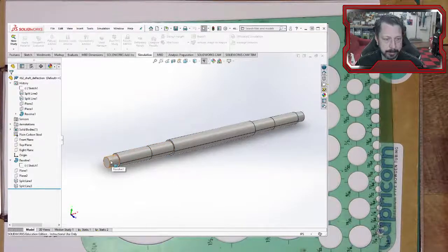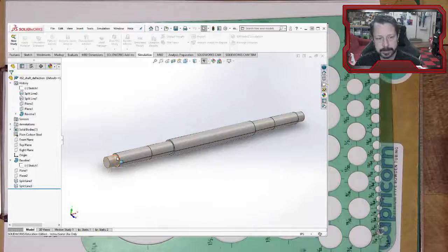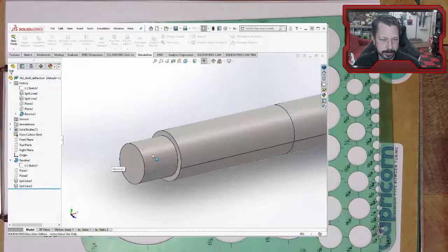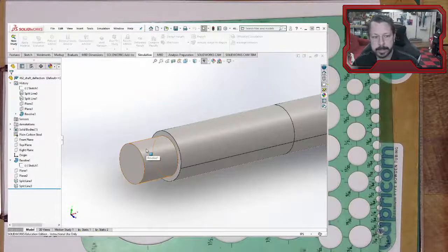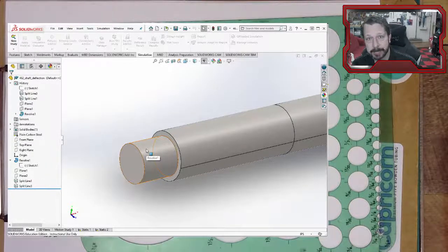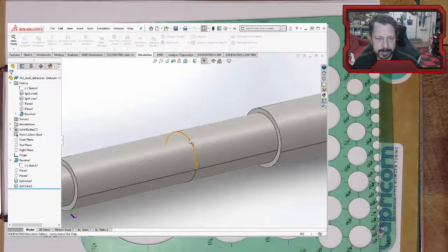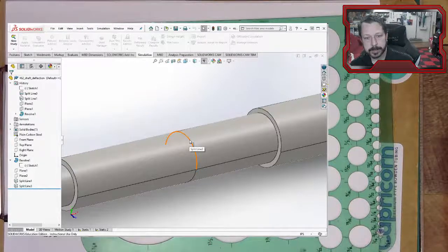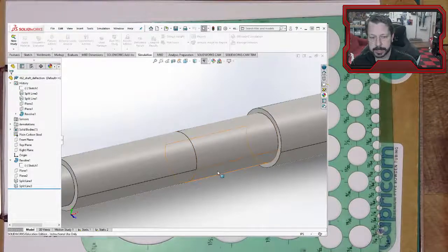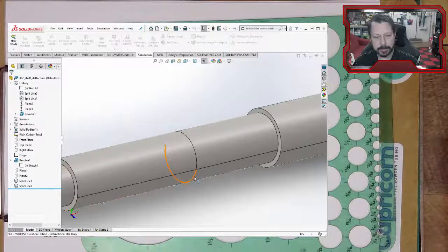Here I've isolated the bearing so that I can create that. And now this one, the shoulder naturally isolates it anyway. But I have an area here, surface, there we go, that I can fix as a bearing fixture in the simulation. And then here, this split line is more or less where the hub ends on the gear. So I'm going to apply any forces that the gear experiences. I'm going to apply them to this and this surface. So that's why this split line and that one are here.